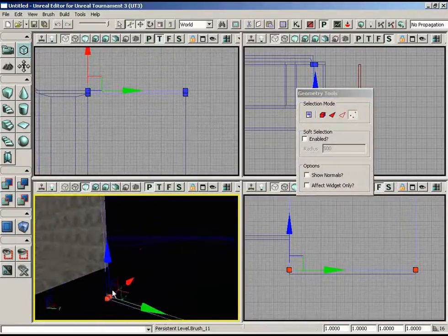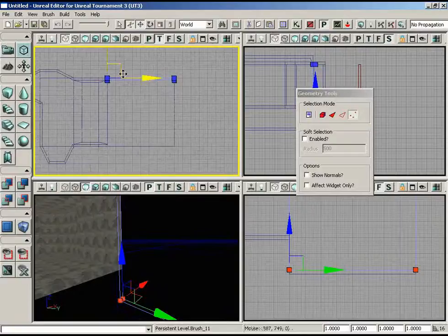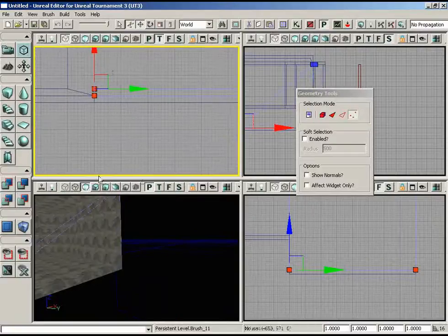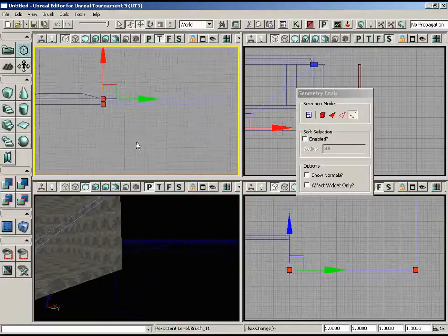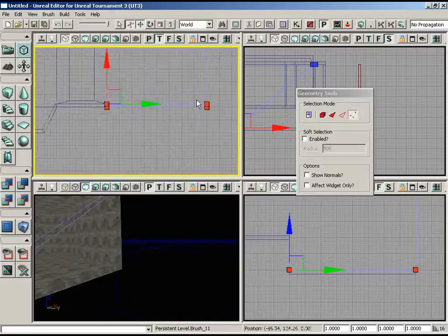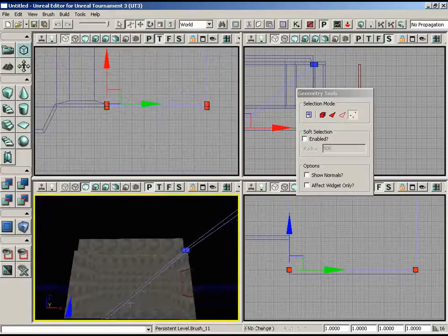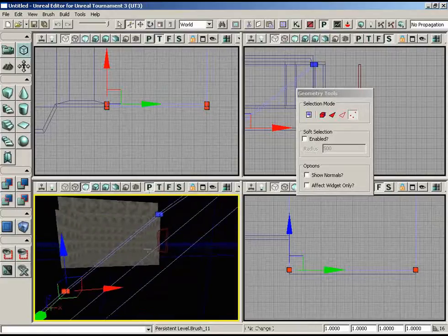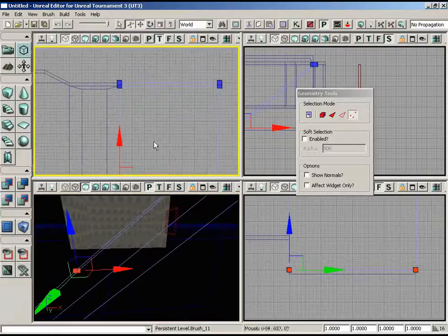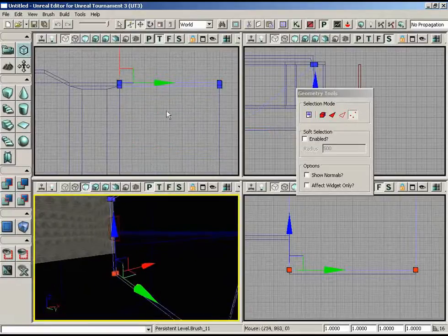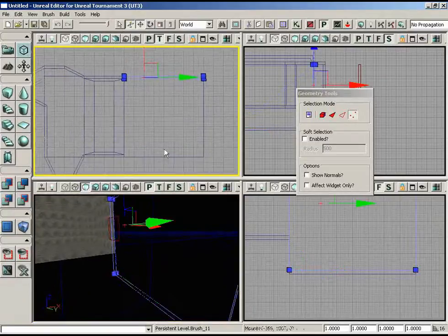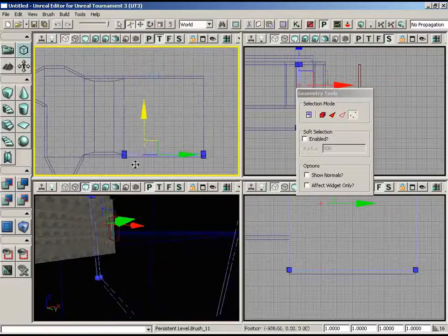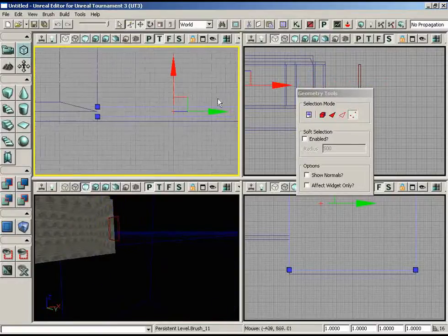So that looks like one wall. It's looking good as far as dimensions, so let me duplicate it to the other side. Drag this over. Let me zoom in just a little bit. I'm not 100% sure that you had reselected. You might want to undo that. Oh, look what happened. Yeah, good eye on that. What had happened is, it seems I was in vertex selection mode, and I grabbed the bottom vertices only. So how about we put those right back where they were, and reselect the brush so we have the entire thing. Alt drag, and that way we're duplicating and not just dragging the bottom vertices.